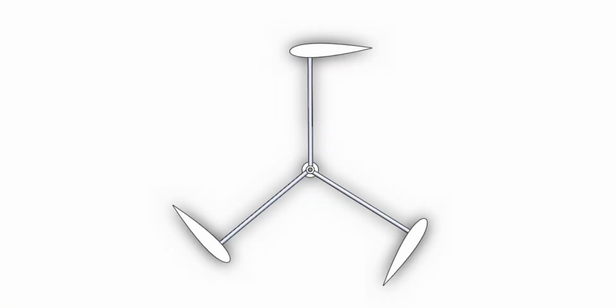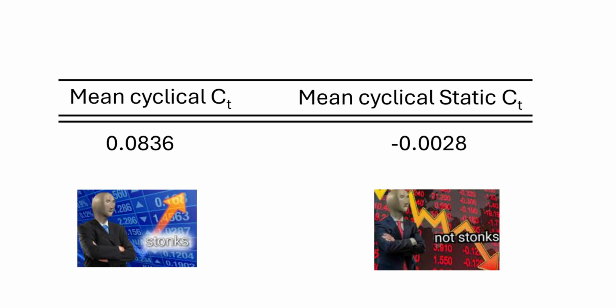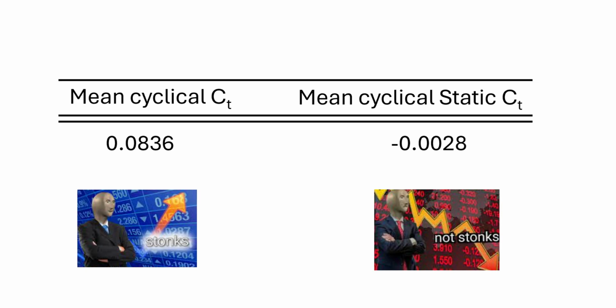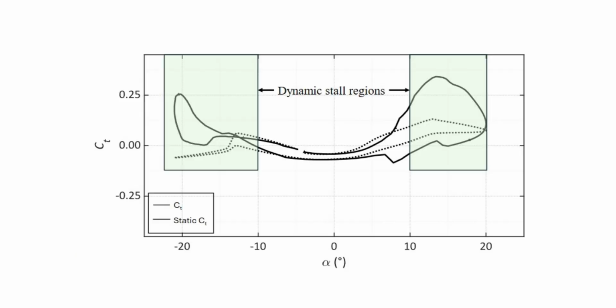If a turbine blade has a negative thrust coefficient, it better have other blades to help make up for it. In this scenario of a single-bladed Darrieus turbine with a negative thrust coefficient per cycle, you can bet that this turbine is going to slow down. Therefore, according to the mean thrust coefficient values, it's pretty clear that dynamic stall is actually a requirement for the turbine blade to generate positive torque, and therefore to accelerate the turbine.